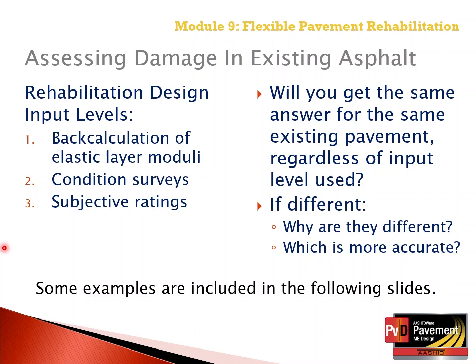The suggestion is to collect as much information as you can, non-destructive deflection testing and visual distress surveys, and use that in the rehabilitation design. And if we see that there is a big difference between the two, we need to stop and define why there is a difference.